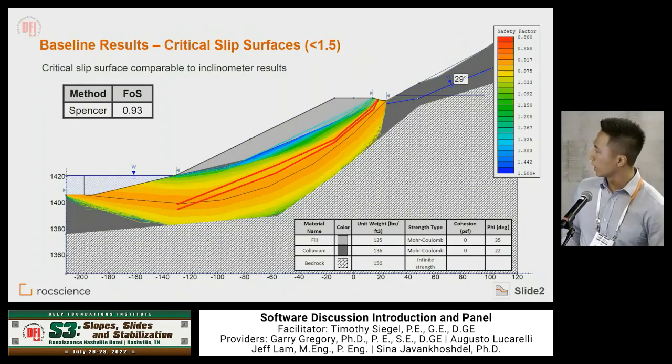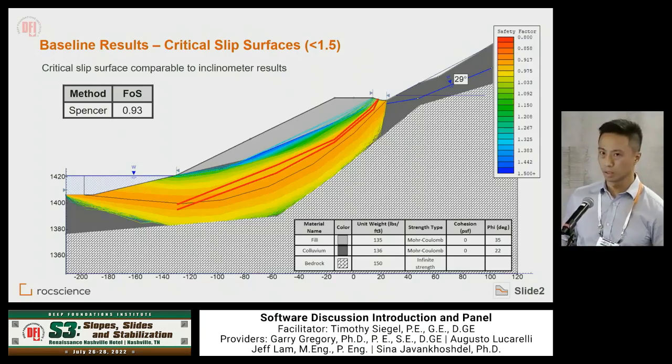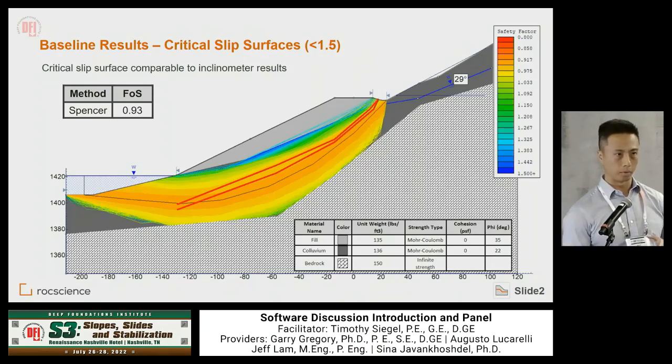In Slide 2, once again, we had to focus on just this area here. So we set our slope limits. And when we first started running Slide 2, we have a new feature called MMO, and it's able to actually tell you in one shot that this area here is unstable, the fill here is unstable, and then also globally is unstable. So you can do all of that at once now without running both a local and a global type of analysis.